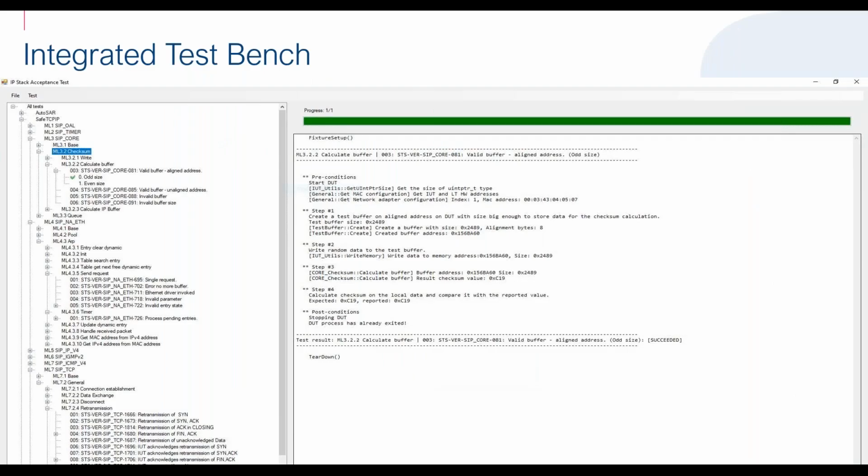And to support that whole process, we have our integrated test bench, which is basically a piece of software that you can write all your test cases in C#. We do this for all the AutoSAR test cases, for example, plus all the Open Alliance TC8 test cases. These have all been implemented under our test bench, plus all our standard test cases for doing coverage, for doing functional testing of our SafeTCPIP modules. We run this test bench, and through remote procedure calls, it logs the test cases, gets the results back, and gives you an output as to whether your software is behaving as it should in its new environment.